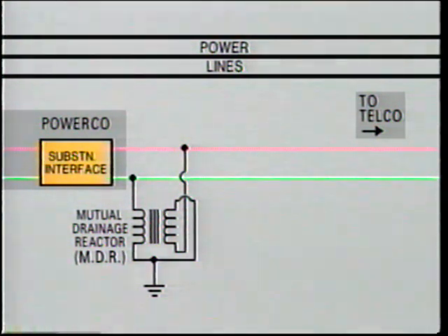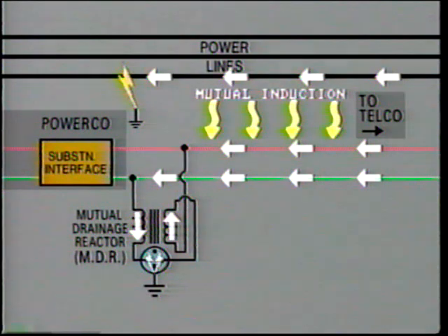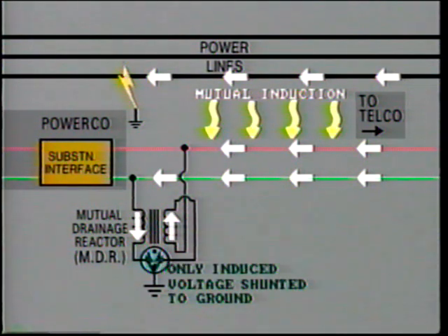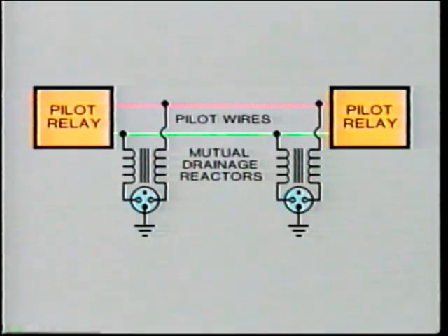In another arrangement, the connection to ground is made through a gas discharge tube. This eliminates any signal loss until the tube discharges to ground on overvoltage. Only the induced common mode voltage will be shunted to ground. Note, AC and DC communication signals are not interrupted during an overvoltage condition.